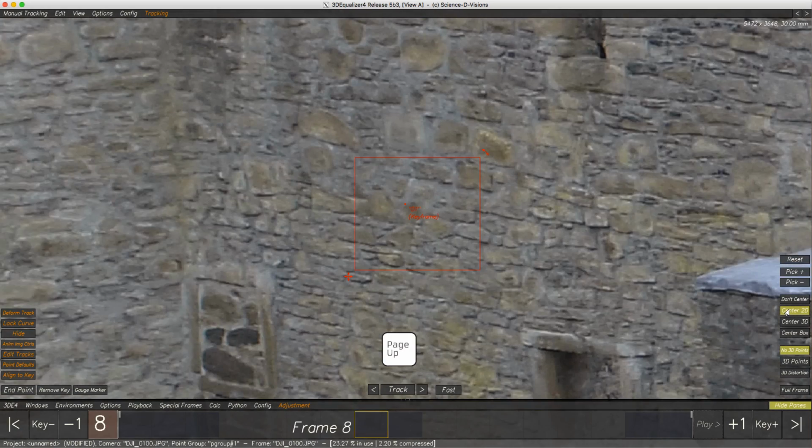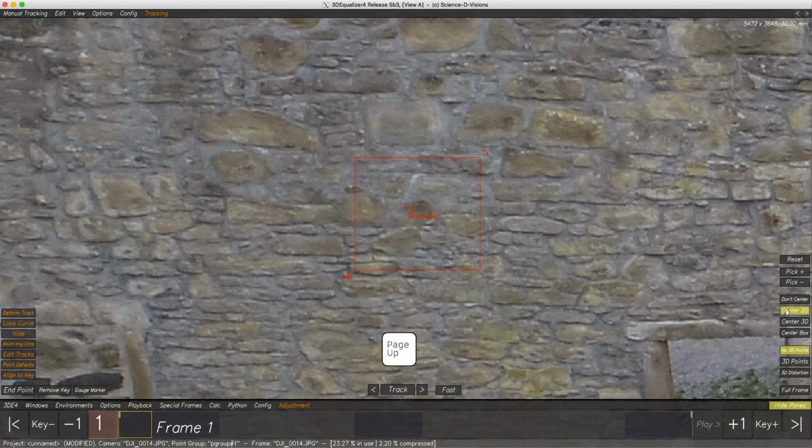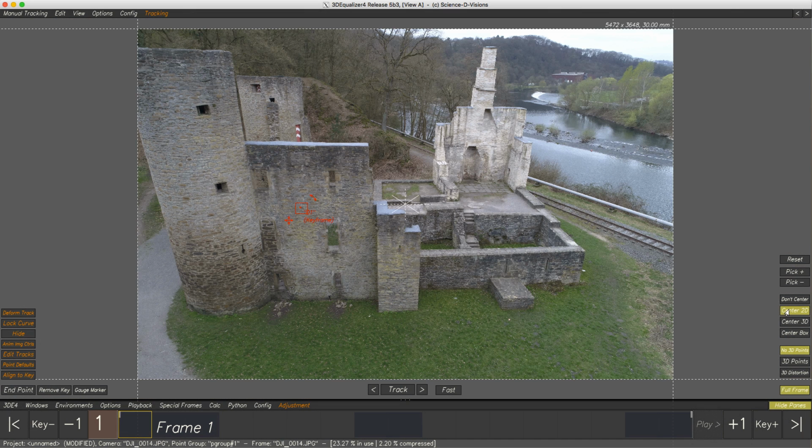Using this precise tracker, we can track so many more features instead of just those only identifiable in every frame by our eyes. Alright, having this opportunity, let's use this moment to discuss some do's and don'ts at tracking in a reference frame project. Let's have a look at good and bad features for tracking. This wall looks good, as proven just a second ago. Also this one. Basically, every wall providing a flat structure is suitable.